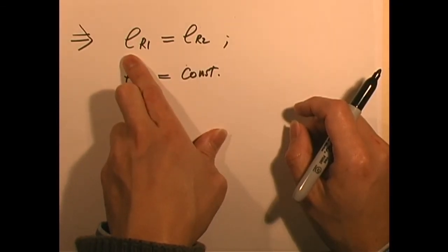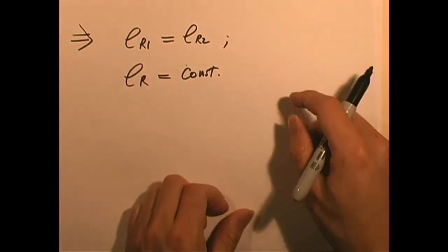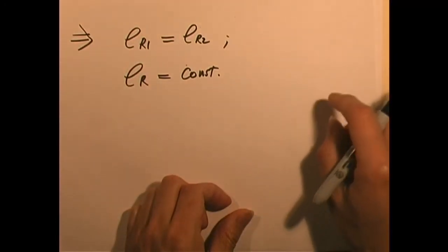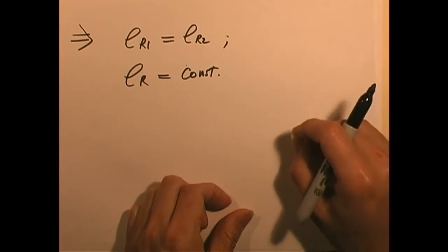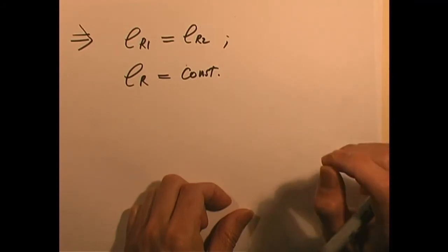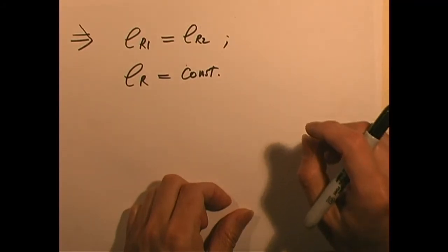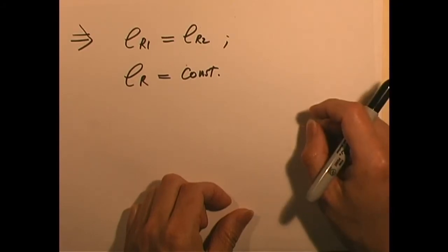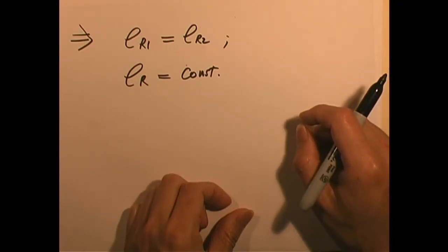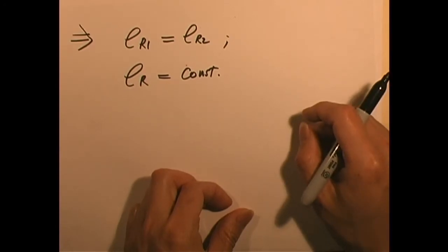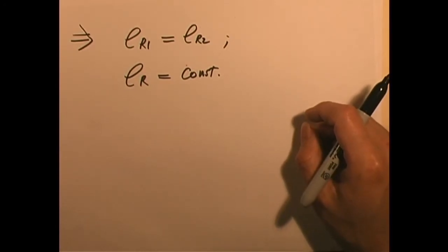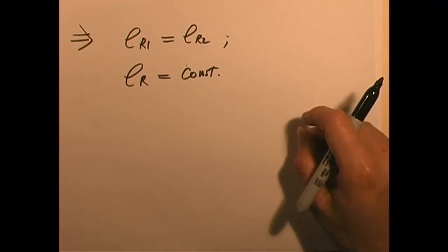So what did that tell us? It tells us that if you look at two temperatures, T hot and T cold, and you design any reversible engine operating between them, these two reversible engines must have the exact same efficiency. So not only is the reversible engine special because it's got the highest possible efficiency, but all reversible engines operating between two fixed temperatures must have the same identical efficiency.